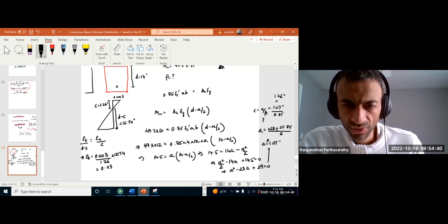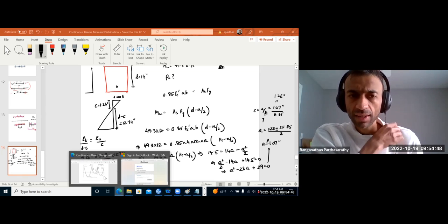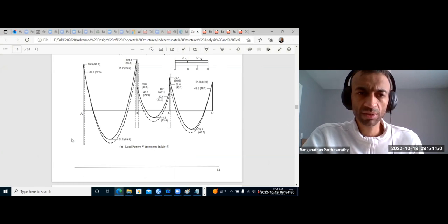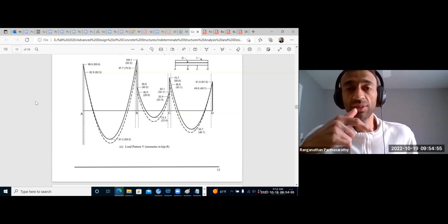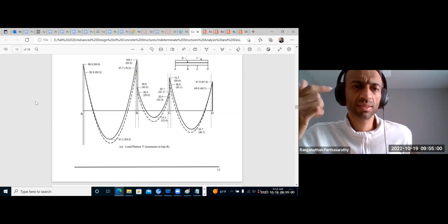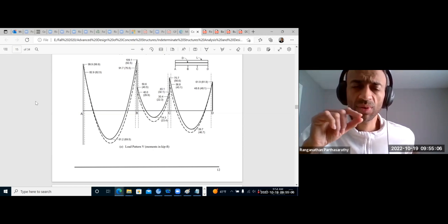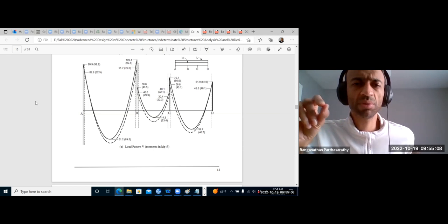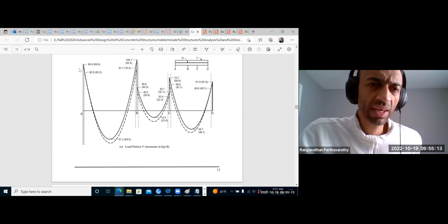Unlike in steel, where we do get an analytical calculation for plastic moments, in concrete we are not doing an analytical calculation. The code is giving us a kind of approximation of that. That is the choice, reducing by either the least of 1000 times epsilon t or 20%. So the dotted one which you see is as if the plastic hinges formed at those locations.